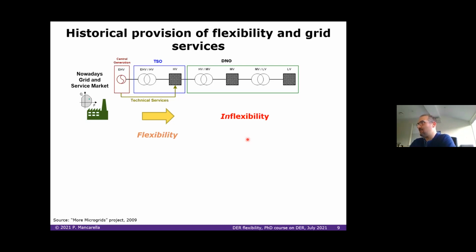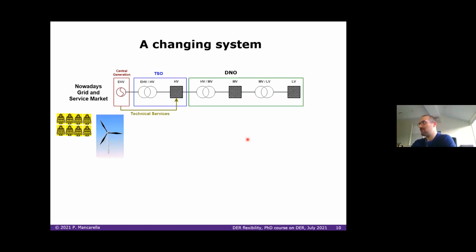constraints. What you would do in the distribution system is basically so-called passive management, since you would not do anything at all. You would resolve the control problem at the planning stage, meaning that you would build the network so big to deal with the worst case scenarios, including some security constraints like N-1 and N-2 in some cases also in distribution networks, so that you would not need to do anything in real time. There's no active system. Then again, the idea of having a flexible system in the distribution network.